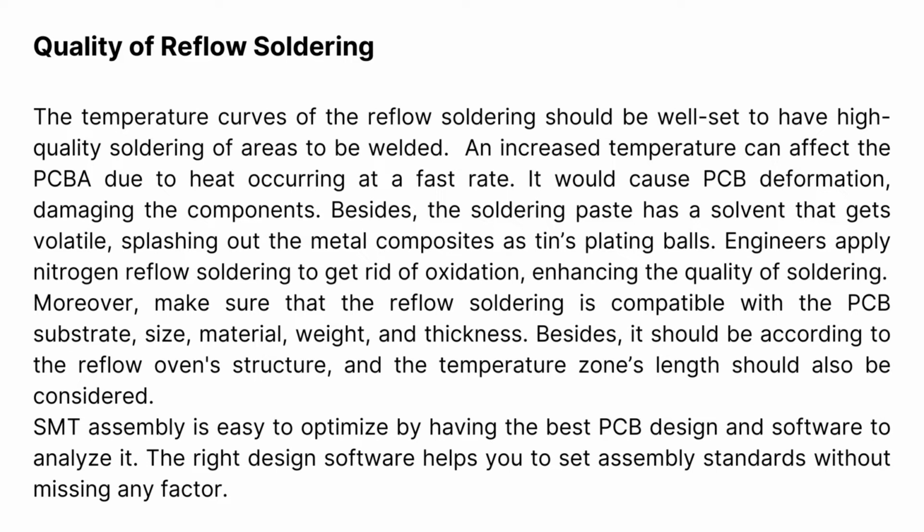Moreover, make sure that the reflow soldering is compatible with the PCB substrate, size, material, weight, and thickness. Besides, it should be according to the reflow oven structure, and the temperature zone's length should also be considered. SMT assembly is easy to optimize by having the best PCB design and software to analyze it. The right design software helps you to set assembly standards without missing any factor.